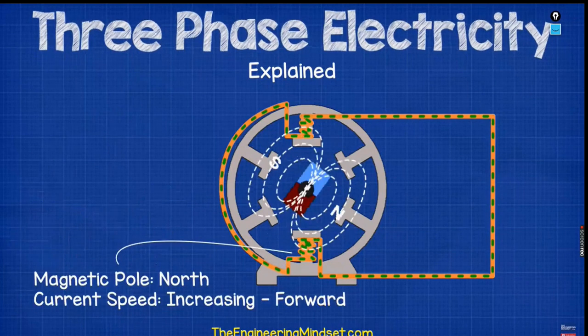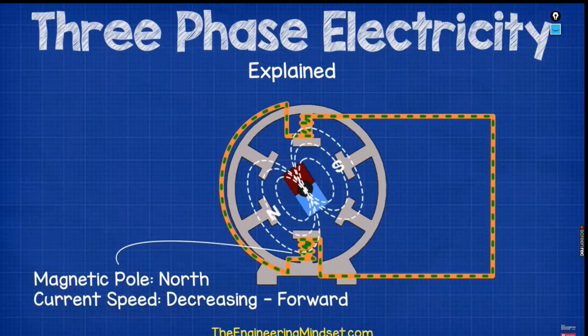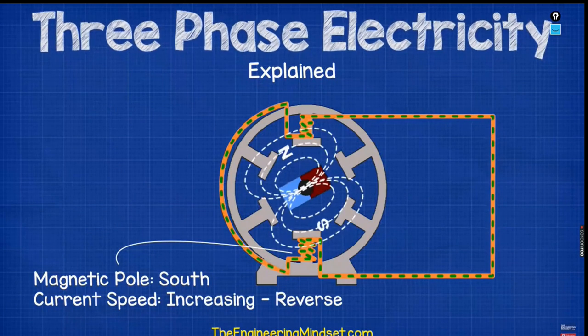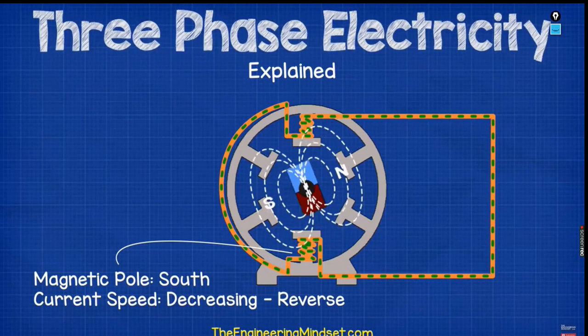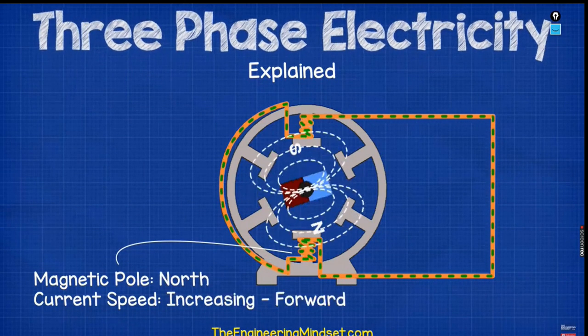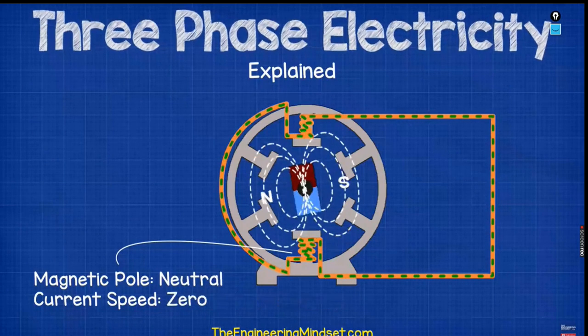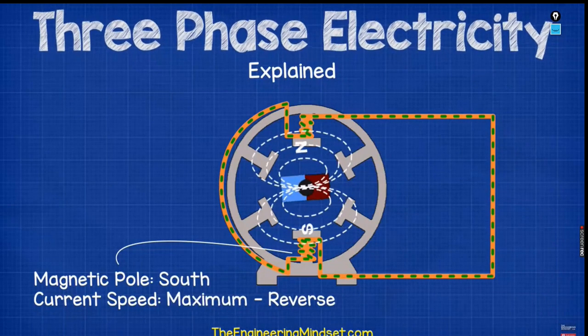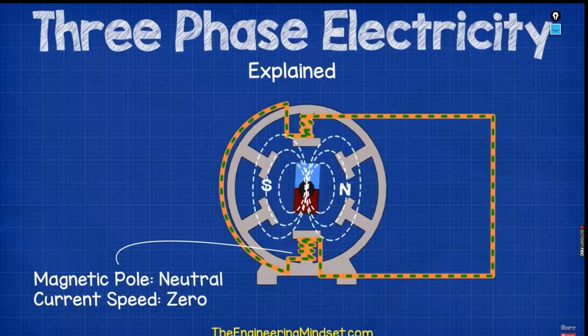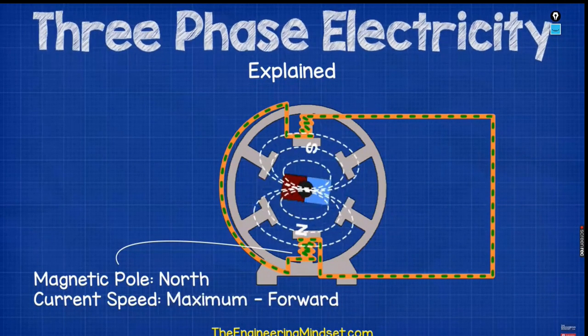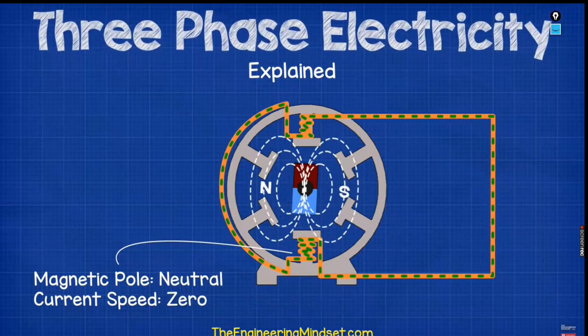Obviously, that leads to controllability of the EMF. The neutral axis gets reversed in each direction whenever the magnet rotates by a particular angle. Then you get a sinusoidal waveform corresponding to the change in the flux linking with that conductor.